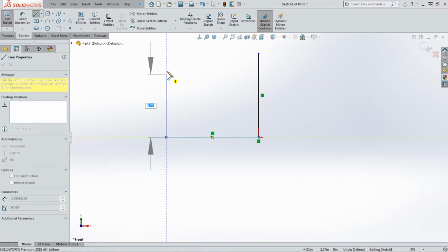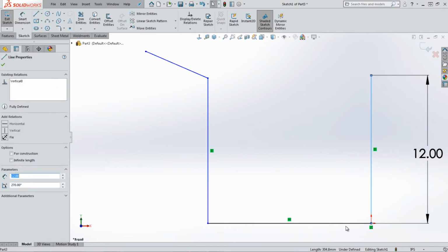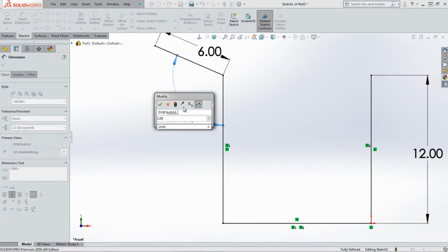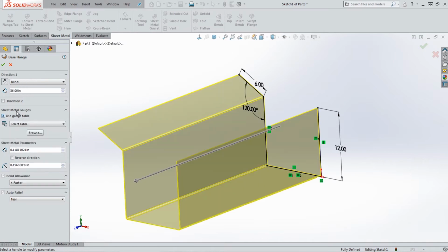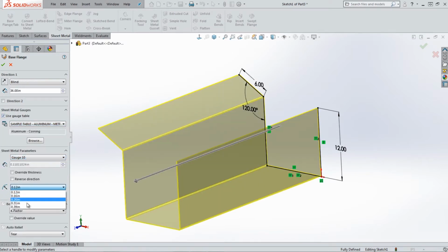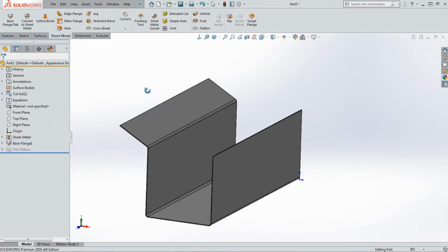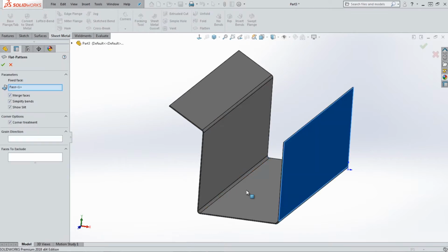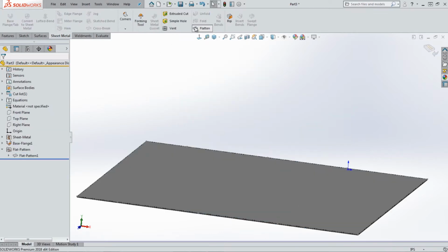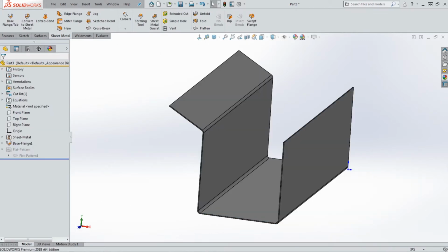water jet, etc. Using SOLIDWORKS easy sketch tools, we can create our initial shape in 2D and then turn it into a sheet metal part using the sheet metal specific tools. We can even use a gauge table that is linked to your own custom bend tables. This way you know the bend allowances are going to be exactly the same as you currently use. No more calculating this on the fly. This also makes sure that the design and flat will be correct the first time. Wasting material with incorrect bend allowances can be a thing of the past.